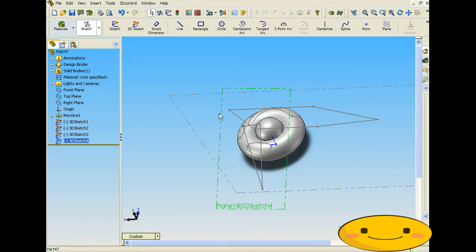So these sketch planes are just kind of like for in here. You can have either one feature that it's going to just make the plane off of, or if you have three unique points, it can be from previous sketches too. It'll create a sketch plane from those. So that concludes our tutorial on how to use the sketch plane feature within Solidworks.